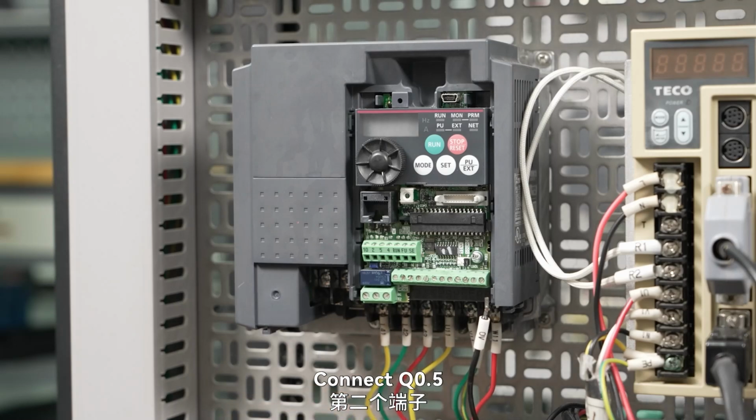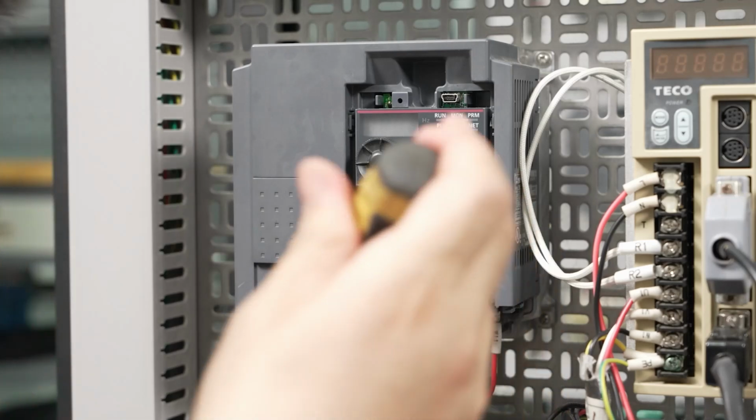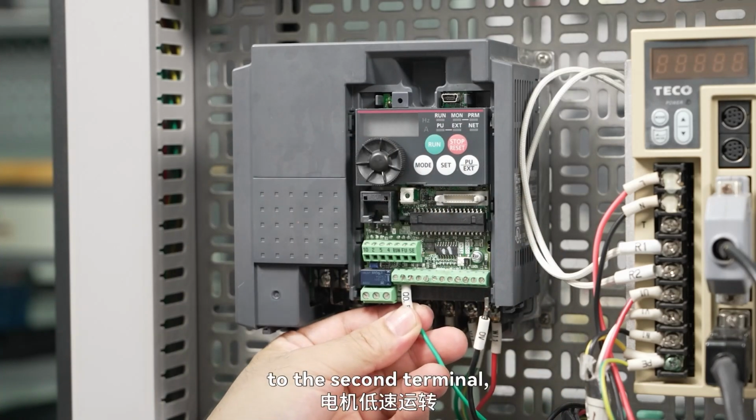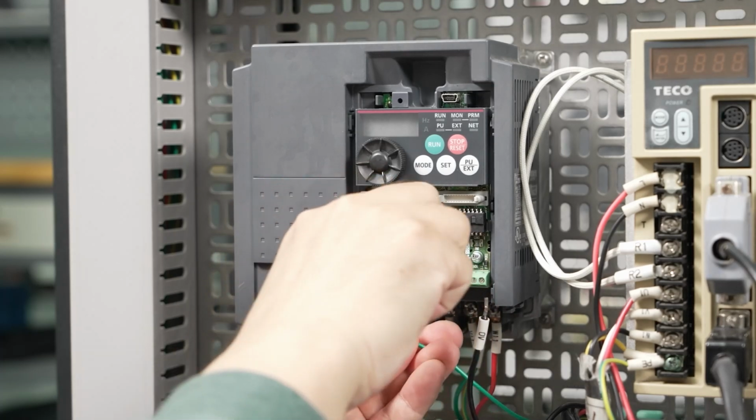Connect Q0.5 for the low-speed operation of the motor to the second terminal, and use a small rotary screwdriver for wiring.